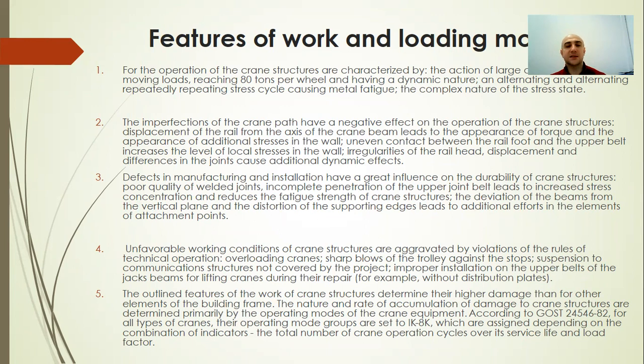This is facilitated by irregularities in the crane tracks and differences at the rail joint. All this leads to the appearance of damage in the crane structure in the form of fatigue cracks, breakdown of connections, loosening of the units, and disruption of normal operation over time.